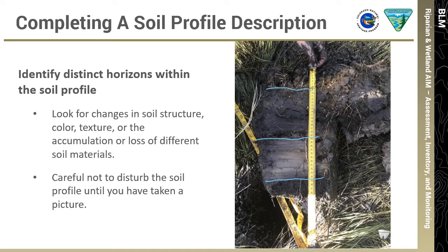Tearing away pieces of soil from the underside of the core can help accurately place the horizon boundaries. After determining the horizon boundaries on the soil core, it can be helpful to check these depth measurements with the horizon seen inside the pit in case the soil core became compacted during excavation.